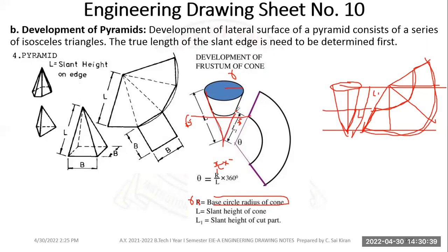Only this circle will be there, and this circle, suppose I draw a line, divide into 12 equal parts, then at this one I have to give this small circle radius here. With respect to this radius, I have to draw the circle. Again, this is the complete r. This is small r. With respect to small r, I'll draw the radius, and with respect to this radius, I'll draw a circle. Okay, I have to divide all this. So this is about the frustum.